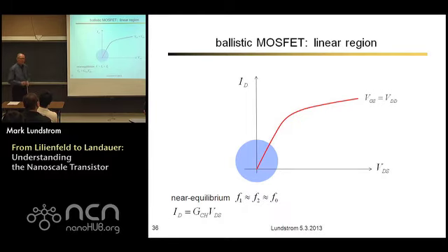Okay, now we can do a MOSFET the way if somebody were encountering a MOSFET for the first time today, 20 nanometer channel length, and they had to analyze it, this is probably how they would think to do it. All right. I know how to treat nano devices. I'll treat my nano MOSFET this way. So we have an IV characteristic. Let's look down here. F1 and F2 are just a little bit different because we've applied a small drain voltage. Both of them are close to the equilibrium Fermi function. So the current is just the conductance times voltage, and we want to compute the conductance.